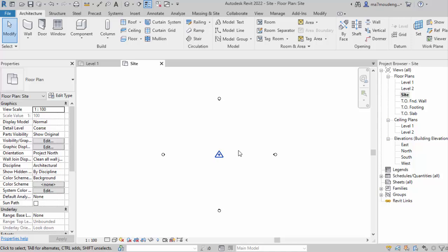So now we are not talking about a straight line between points, we are talking about curved lengths. That's why Revit has a limitation, to keep the accuracy. So if your file is too big and you bring it into Revit, Revit will give you an error that this file is more than 35 kilometers in diameter, so you will not be able to export it. So this is the first thing.